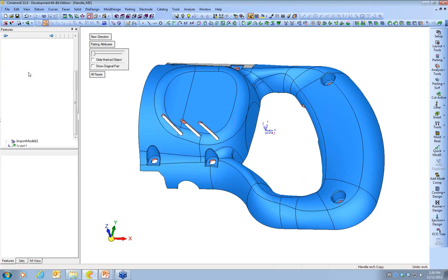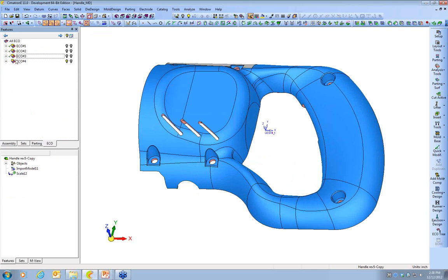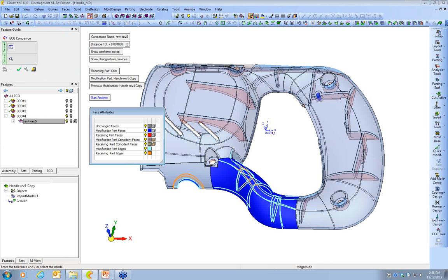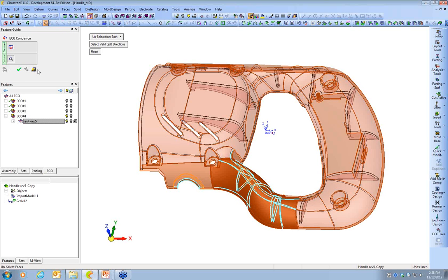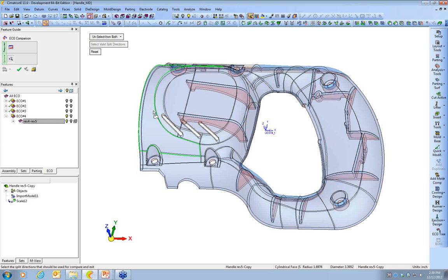And once that's accomplished, we're going to go back to the existing comparison and edit. So remember, these are the results we saw a moment ago. But what we're going to use here is an optional step. And this optional step exists for manual interaction with a comparison result. For example, I could just unpick one of the faces from the new revision that I didn't want to implement. But in this case, we can do a lot better than a manual selection, because I can ask the system to take away any faces that are not relevant to the set and to the block I want.